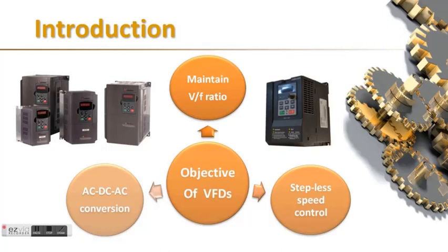There is also a dramatic change in the performance due to the improvements in semiconductor switching devices. The ratio of voltage to frequency written on the motors is entered into the VFD in order to have proper power factor. This also reduces excessive heating of the motor. The main objective of VFD is to use a sophisticated microprocessor to maintain the voltage to frequency ratio.